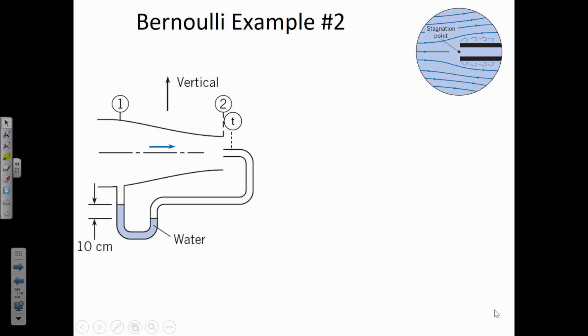Now let's make sure, first of all, that this makes intuitive sense, the fact that it's lower on the right than it is on the left. Do you see how the air coming through this contracted section is basically blowing into the opening of that tube? And so it's stagnating. Once it gets inside the tube, this is a static manometer. Manometers don't have fluid flowing through them.